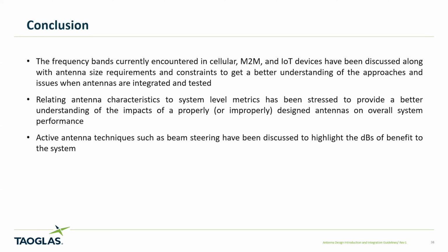Okay. So one last question about MIMO that is kind of related. Do MIMO antennas on the client side in 5G steer according to nulls, or just toward the direction of signal? When we talk about MIMO, it's ideally orthogonal multiple streams. But we also know that in practice, as you're bringing up, you can beam steer. The question is, is it more common to steer a null in 5G multi-antenna techniques, or is it more common to increase the gain in the direction that's advantageous?